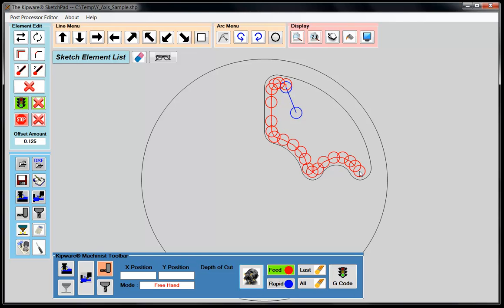And again, when we get into the conversational screen, we'll be able to do this at depth of cut as well. I'm going to change back to rapid mode, and I'll come back someplace to the start point. Okay, so I created my kind of semi-finishing toolpath using the Machinist mode.